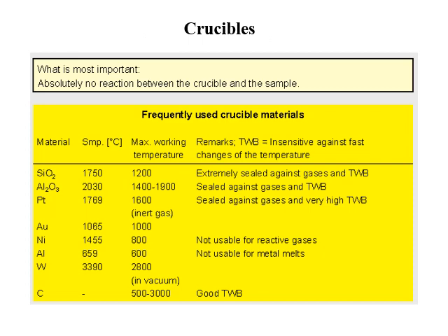Here's an example of some of the crucibles that are used. Crucibles are available in all kinds of materials, ranging from silica to alumina, platinum, gold, and so forth. I think for the most part, most people use platinum crucibles because they have a very high max working temperature. As this slide says, max working temperature up to 1600 degrees C, and they're non-reactive.